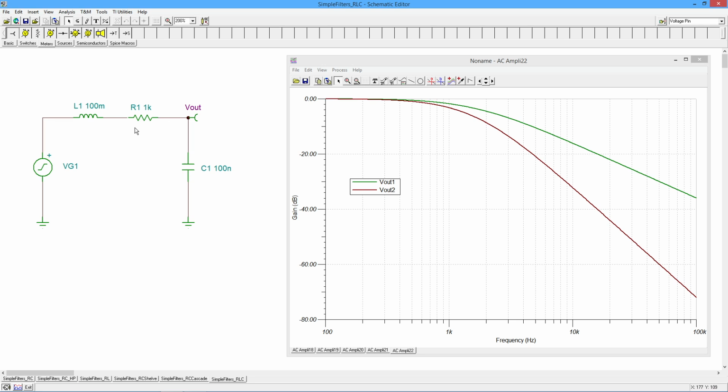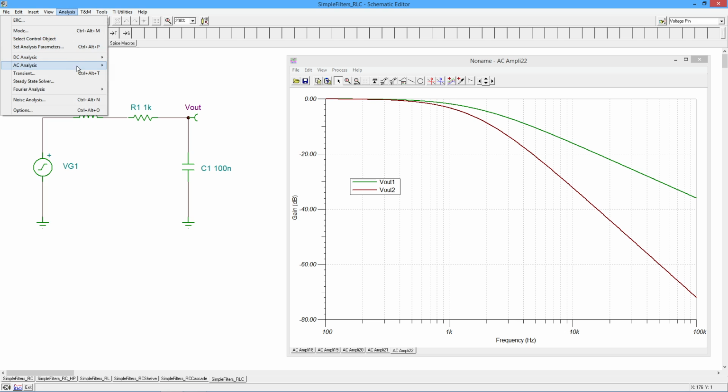Now, what ends up happening in a little series resonant loop? Well, you get a response that has a little peak around the resonance, depending on what the damping factor is, what the Q is. Damping is the reciprocal of Q, the quality factor, and that's essentially looking at the ratio of your X sub L and your R value. So as I adjust the R value, we can change the peakiness, if you will, of this output shape. All right? So let's do analysis on this.